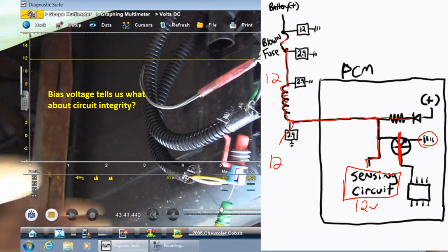So diode blocks it. This comes over this way. So I have 12 volts sitting here right now. This is a working circuit. This is what it should do. This is what we see. Normal off voltage readings, 12 and 12. Do I know anything about this right now? I don't see it. It's not there. This looks like a normal ground side switch circuit that I've seen on a million cars.